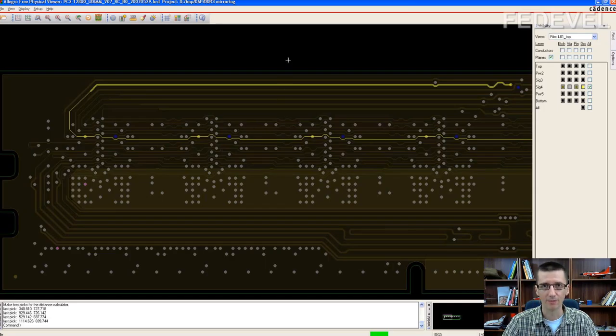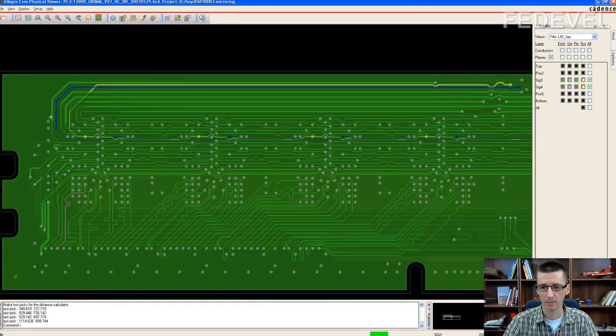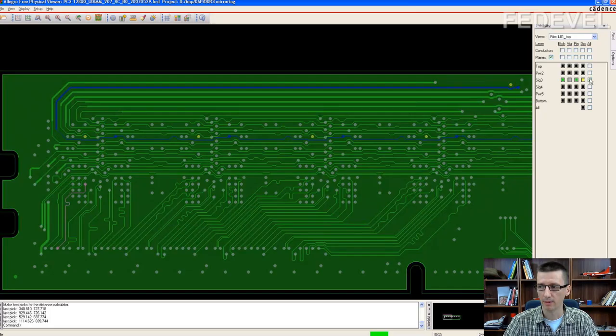You can use this if you know what you are doing. You can use this if you have 3 layers available for address, command and control signal routing, because you need one layer to go up and then you need 2 layers to connect the memory chips between them in parallel. I sometimes use this technique because it speeds up the layout process and it's quite easy to do.